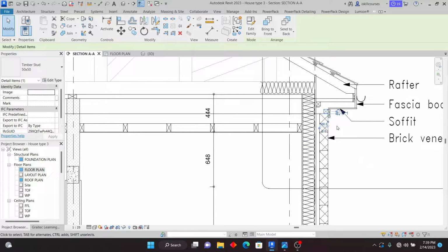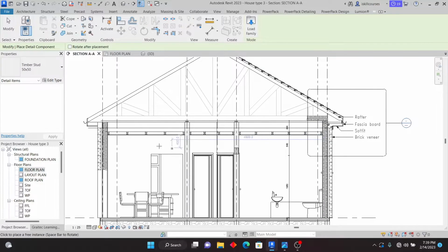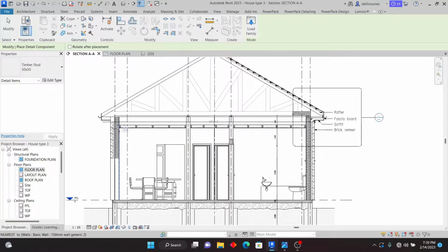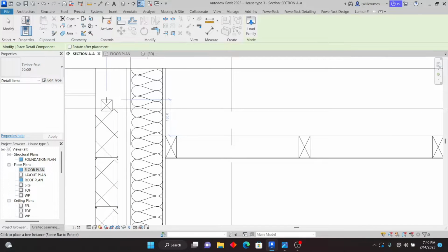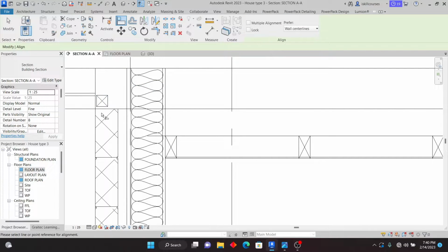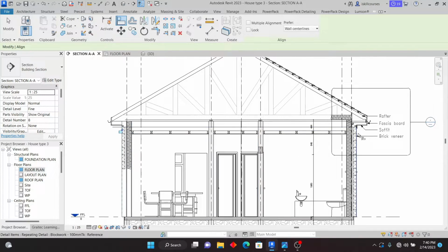All right, so I'll right click and then create a similar one. And from here, I want it to rest on the far left there. I'll place it right here, just like that. Right click, cancel, and I'll type AL on my keyboard for aligning this one and that one. Then click that line and click the edge. As you can see, it's aligning right here.